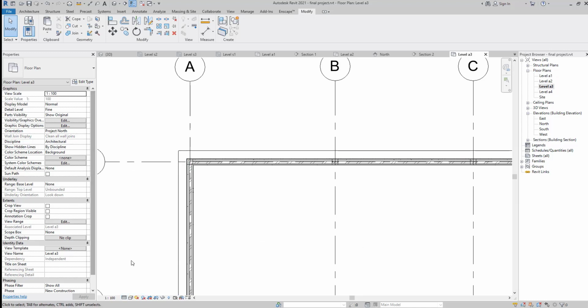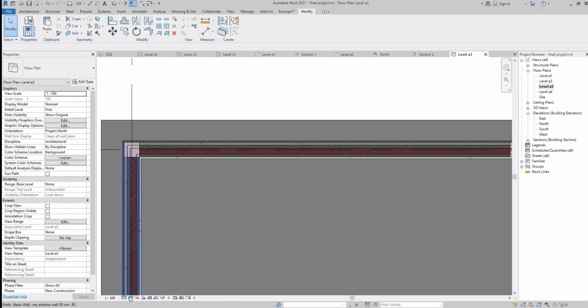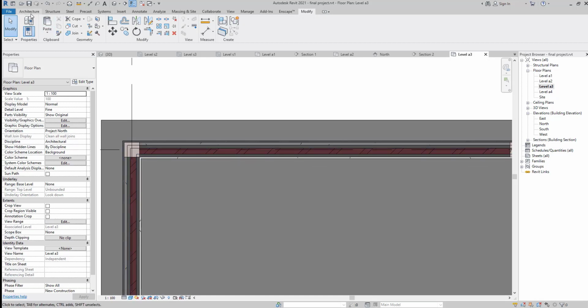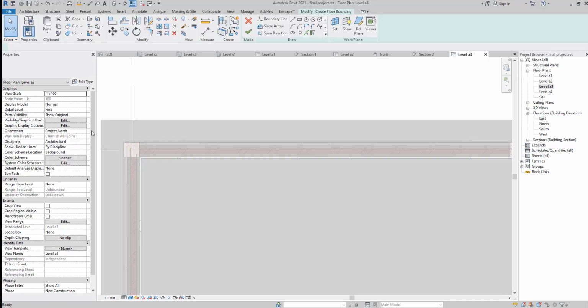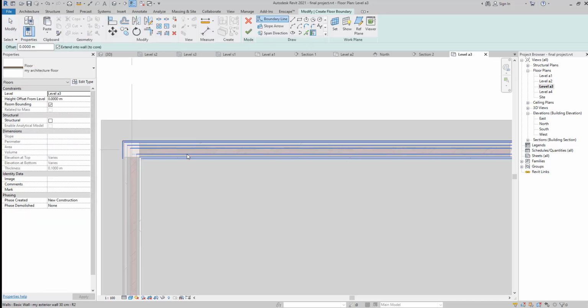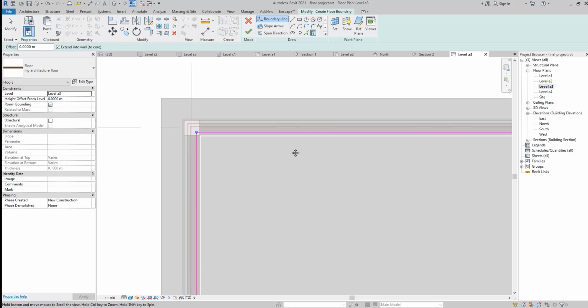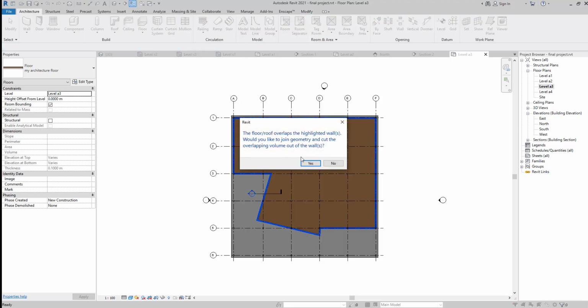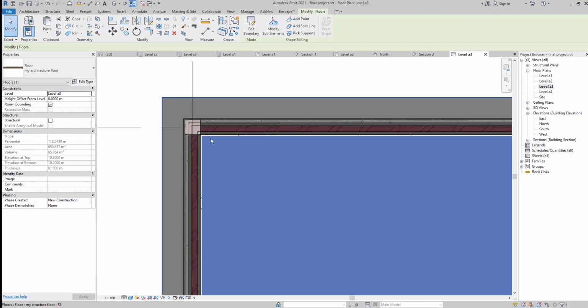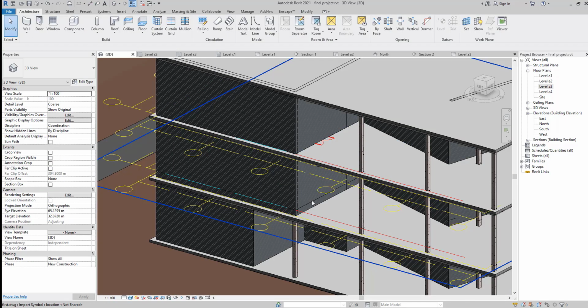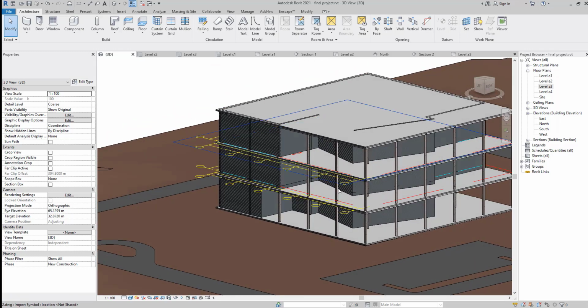You just need to choose your fine and one of these constraint colors. Then we are just going to choose our floor here, simply architecture floor, pick wall, and we are just going to click on Tab, and here we go. Alright, our floor here is also created without any problem.